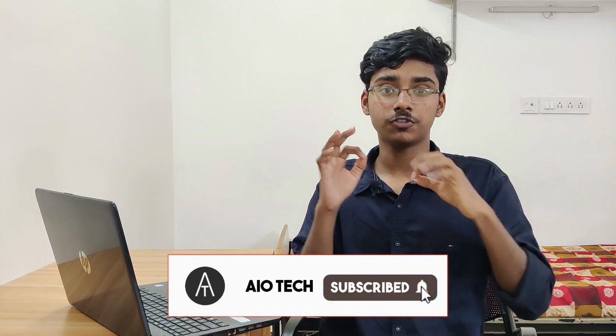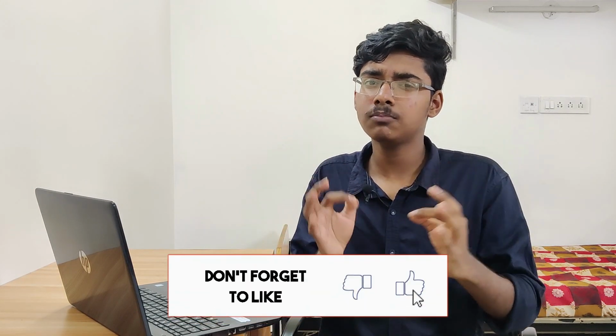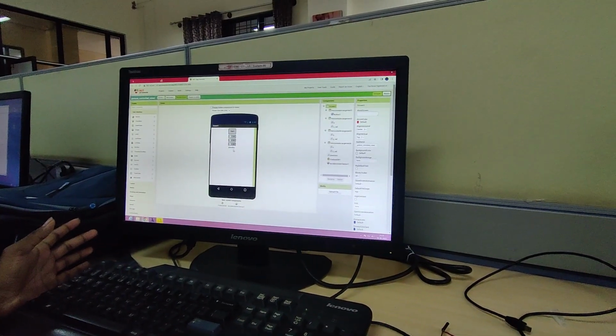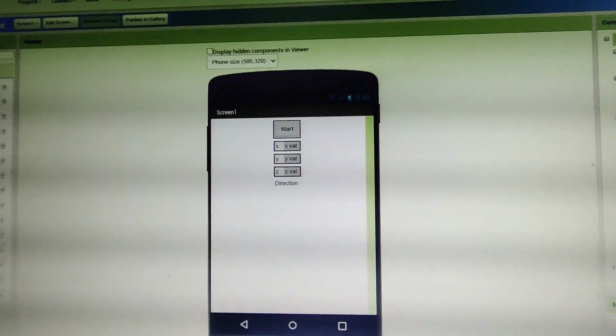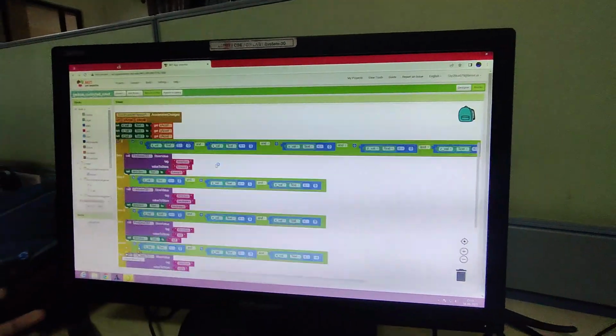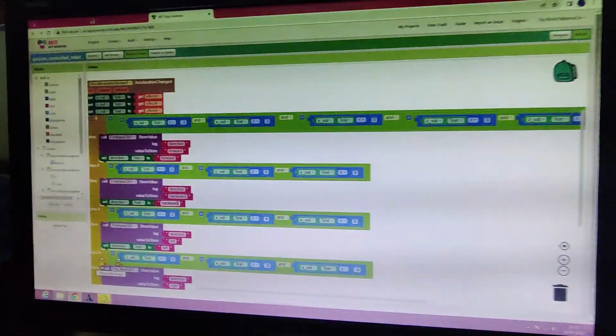We had an issue. The motors were rotating so fast that we couldn't control its speed and eventually the pins were getting damaged. So all we had to do is control the speed of the car. Luckily we had some time to spare and we thought to manually control the speed of the car. For that we need to use analog pins, as analog values vary from 0 to 1 whereas digital has only 0 and 1 values. We created a new speed component in our app and the speed values are being sent to the database and being retrieved to the PC and we rewrote the code.